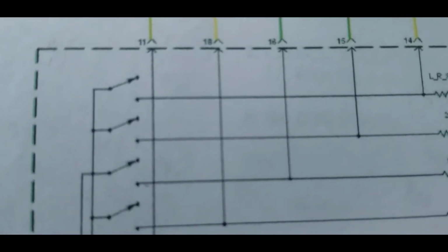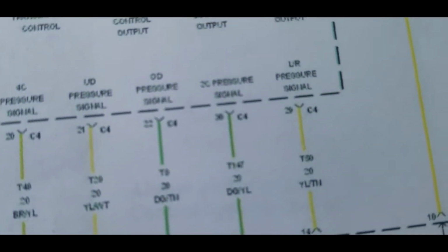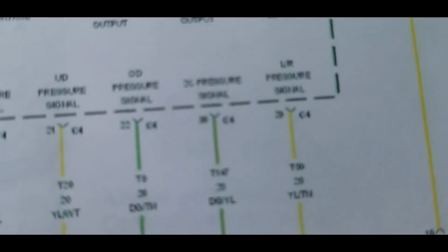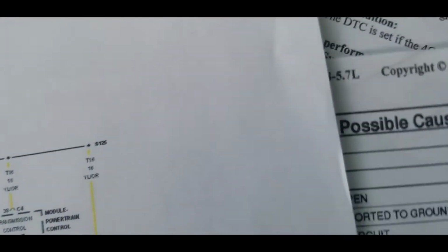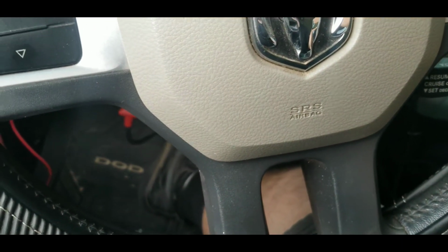When this switch is closed by pressure, the computer watches those voltages go away. If it goes away, it's assuming that it has pressure and a closed switch. So if it commands the pressure to go to another point, like say it turns on the 4C or the 2C clutch, and the way I understand it, that's slipping. It can't even climb the driveway. It's still in fourth gear. Let me cycle it so it'll go back to first gear and it'll drive up my driveway.